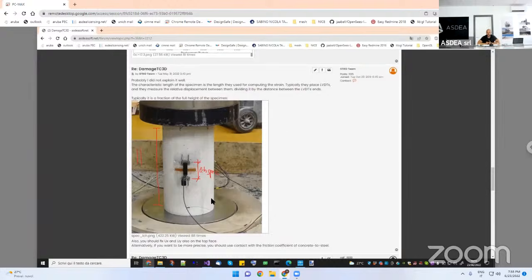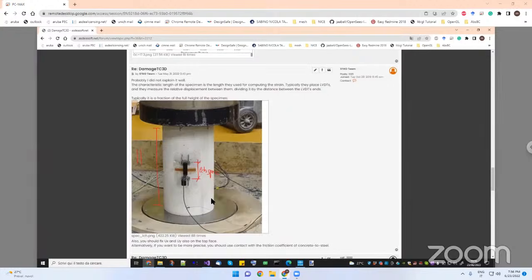Sometimes also when you have a lot of steel, the regularization is not going to be a huge problem because you have a lot of steel there. So it really depends. But if you obtain the real fracture energy from an experiment, you should always use automatic regularization. Now, in your case, probably it's fine because they gave you a specific fracture energy which was already calibrated for that finite element size. So it can make sense, but it's not a general rule, okay? Okay. Thanks a lot.